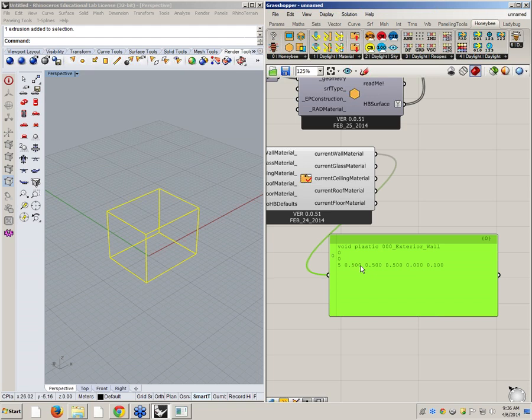It's an RGB reflectivity, so it's a 50% diffuse reflectance wall. Now from this number, okay, let me tell you later. So this is how you read it. Void basically is the start of the line. Then you have plastic. Plastic is a keyword in Radiance that tells you it's not a transparent material.